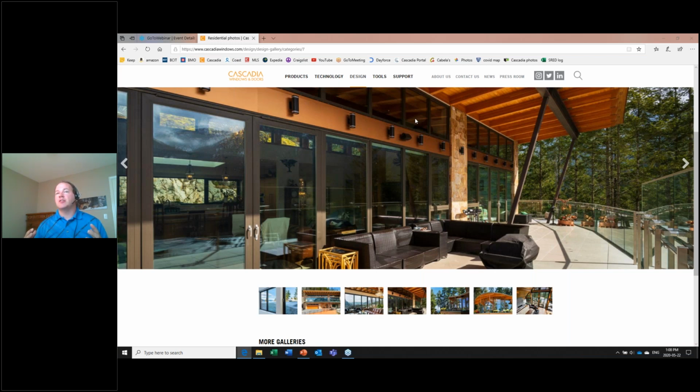But if the stair is fully inside of a firewall that's surrounding it, and then you're just asking, could the outside surface of that firewall that encloses the interior stair have fiberglass windows down it? I think in some cases, yes. But if you have a specific example of that, feel free to contact us, and we can actually recruit a little bit of advice from our fire code consultants to supplement our own internal technical support that we can offer to any client. So really interesting question there. Thank you for submitting that. Sorry I can't answer it definitively, but if you'd like to contact me afterwards and continue that line of conversation, I welcome you to do it.